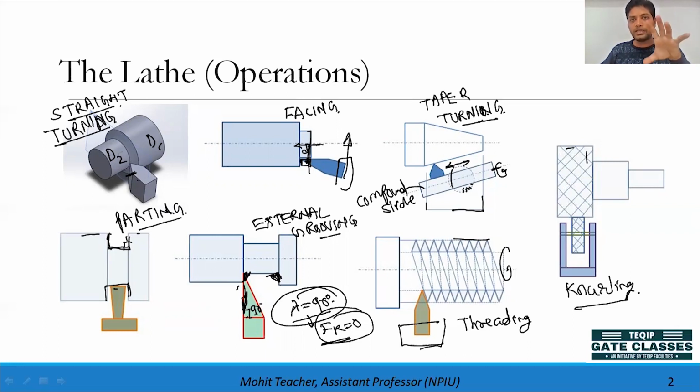Okay, rough does not mean I cannot hold it. Rough in the sense that we are making some holes over there, but in a systematic way. So basically, this is a knurling tool, which is available in the market. It has good hardness and is generally made of HSS. This is mounted on a shaft. This is a complete assembly.